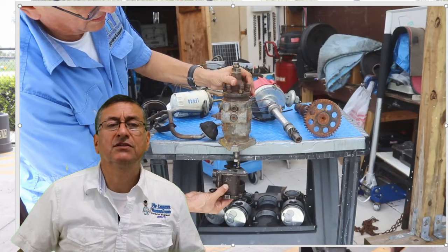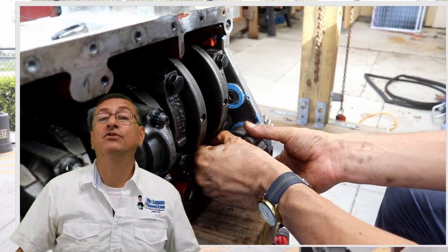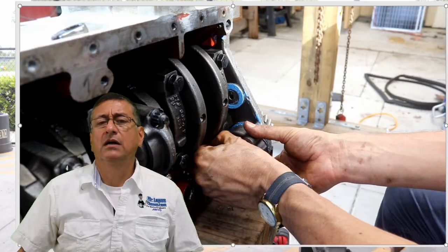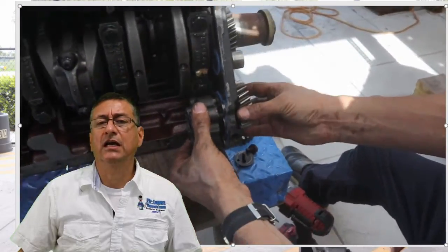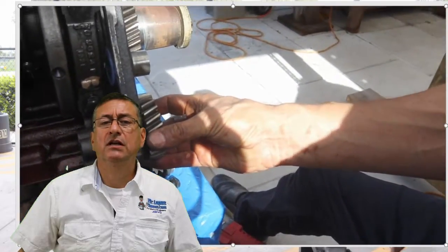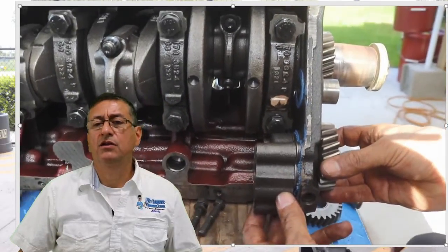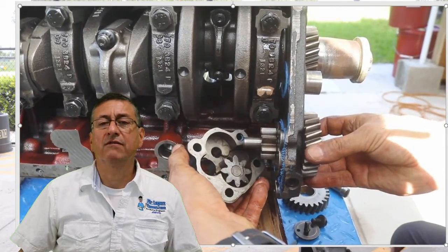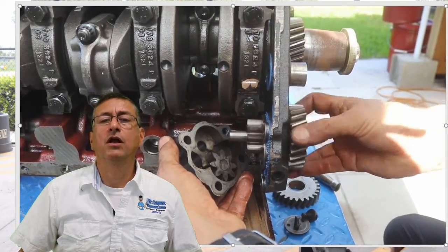This is the specific situation in that case. Now I am going to explain the procedure to remove the oil pump. Removing the oil pump is very easy. You just remove the bolts, and on the other side are located the gears that engage with the crankshaft and camshaft. It is a simple procedure. Immediately after you remove the bolts, you can open the oil pump and see both gears located internally, the driver and driving gear. This is the procedure to remove that oil pump.